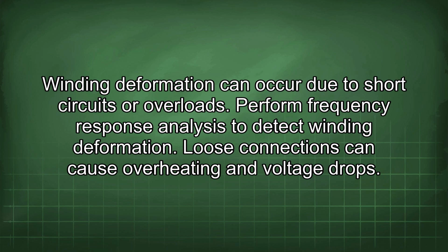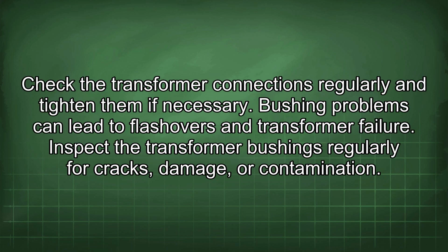Loose connections can cause overheating and voltage drops. Check the transformer connections regularly and tighten them if necessary. Bushing problems can lead to flashovers and transformer failure. Inspect the transformer bushings regularly for cracks, damage, or contamination.